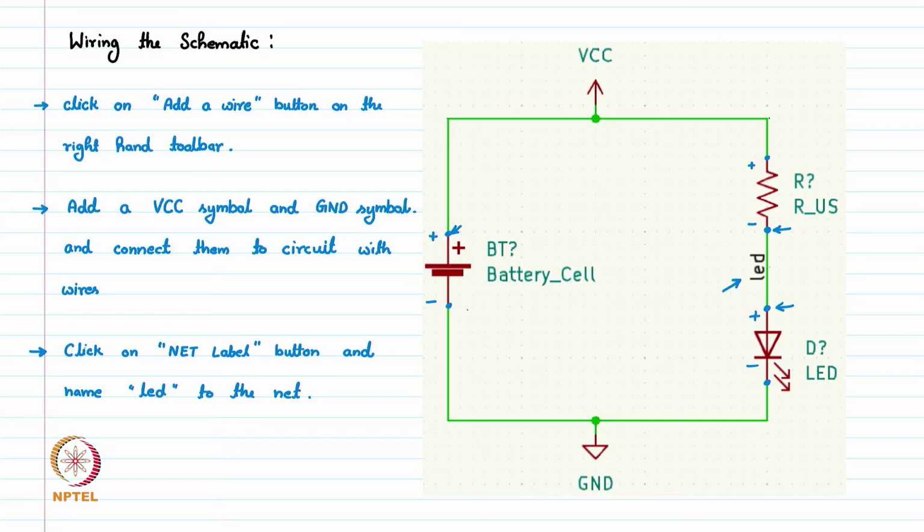However, this is very important to note here: if I have a wire which I give the name LED here, it means this wire I want to call LED. Now, in a bigger circuit, if somewhere at another place I am using one more wire and I give the same name to that wire also, LED for example, in this case there is another circuit.